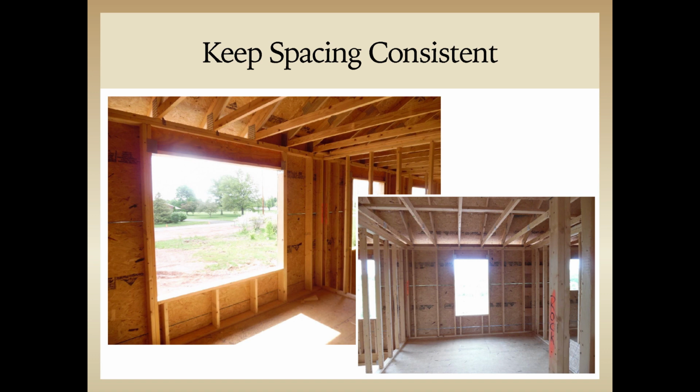This optimization can be seen by comparing these two photos. The one on the left has three 24-inch spaces and one small space. So that's going to require only one piece of insulation be cut. The one on the right has two small spaces requiring twice as much cutting and potentially creating more waste. So making changes like this really show that you're thinking about how to optimize all materials and processes.